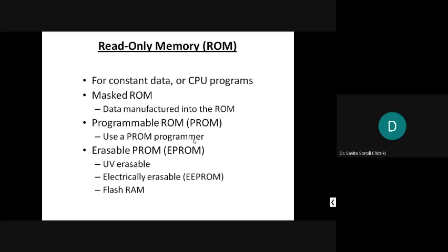Once you have written your program, you remove any logical errors. Then you simulate it by giving the test vectors. Whether the program is working properly or not, you give input waveforms and check the output waveforms. If it is okay, you send it for programming. Once the hex codes are generated, you put them onto the target board through the JTAG cable. There the target board will be either a CPLD or an FPGA.